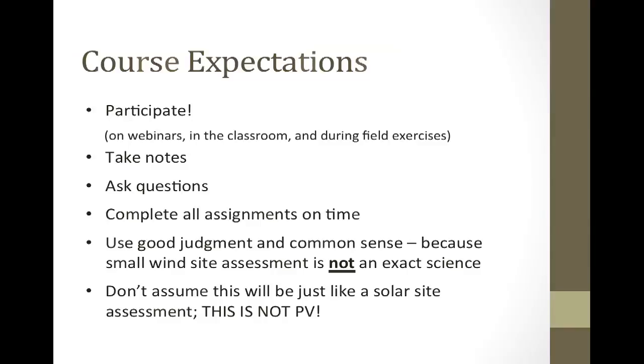So this next bullet's kind of interesting here. Use good judgment and common sense. Boy, you can't teach that. You can't teach that at all. Wind site assessment is not exact. There's a lot of guesswork involved with it. By comparing it to what a PV or solar electric site would be, it's a lot more cut and dried because we have better models and better understandings of where and when the sun is going to shine at a particular location.